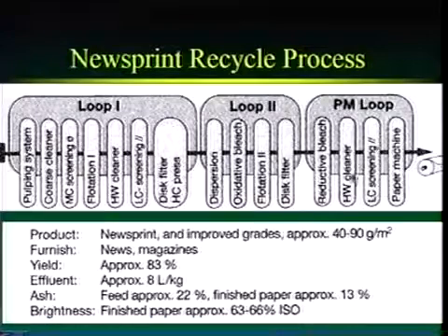Then we want to do two operations, cleaning and screening, and these two operations are used to basically protect the paper machine. We'll try to remove sand and grit and those kinds of materials here, and the low consistency screening will try to remove any residual stickies or contaminants that might foul our paper machine. So that's our system, and we've got our three sections.